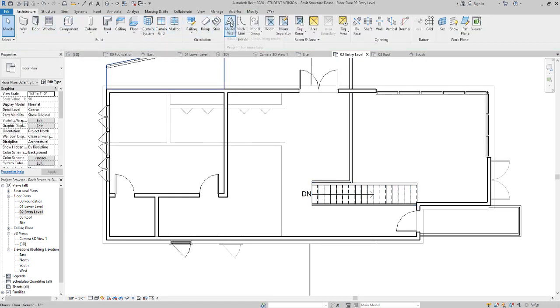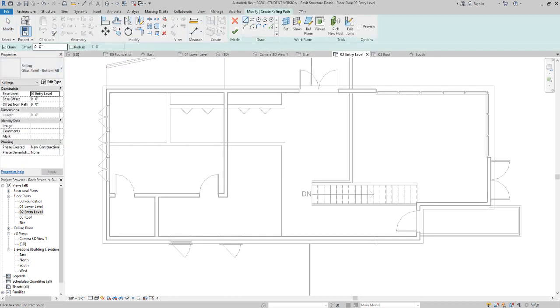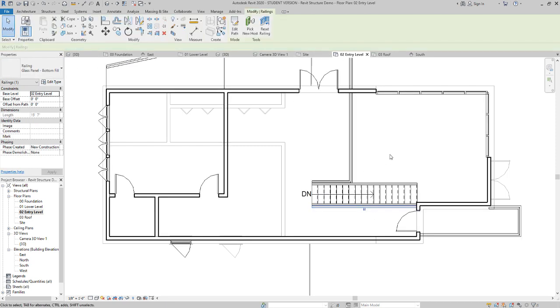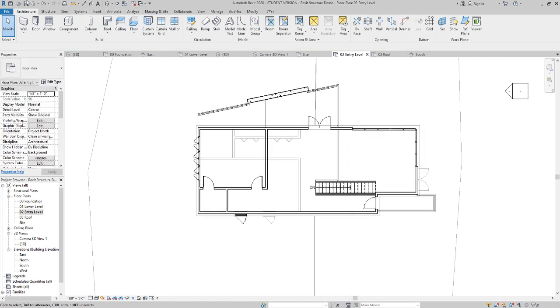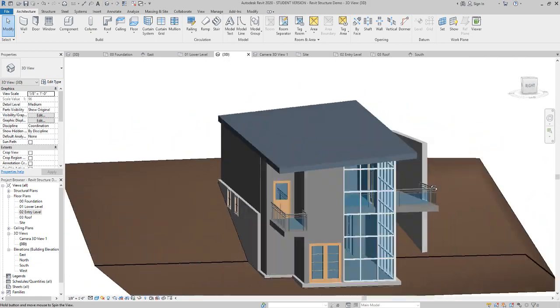So railing and glass panel, 4 inches. Pick lines, go to the inside, and check that off. Click off, and then say save. Once again, if Revit's crashing, just avoid the railings. Alright, cool. So now that looks pretty good.